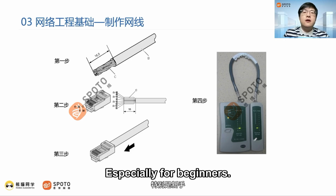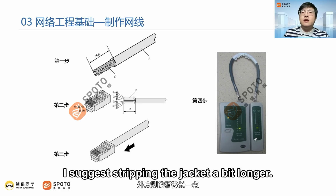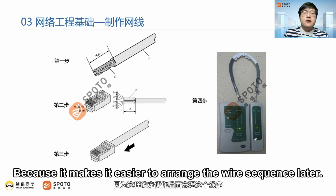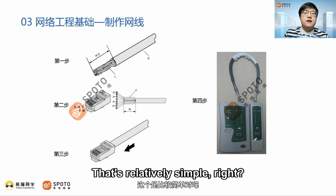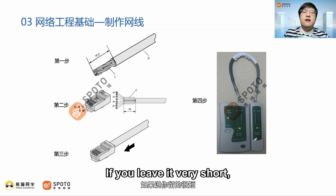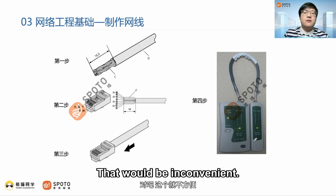Especially for beginners. For your first time or first few times making cables, I suggest stripping the jacket a bit longer, because it makes it easier to arrange the wire sequence later. It makes arranging the wires relatively simple, right? If you leave it very short, the wires might get messed up while you're arranging them, right? That would be inconvenient.